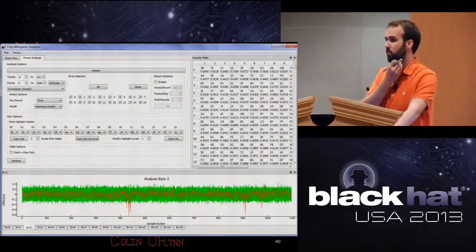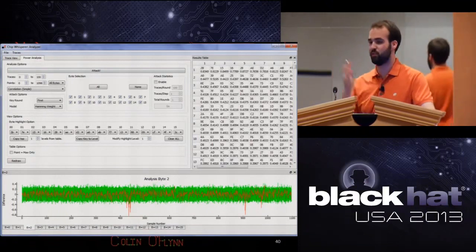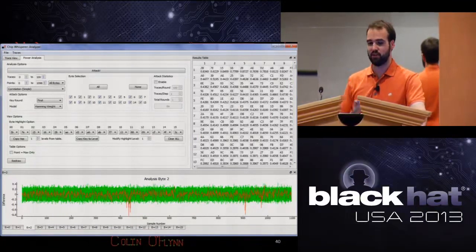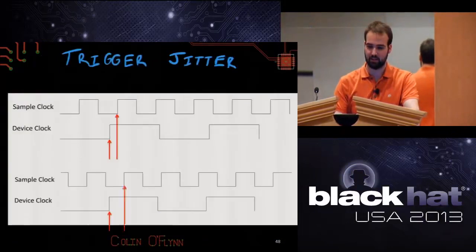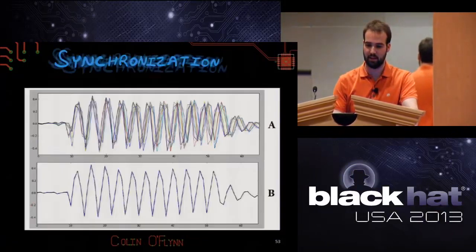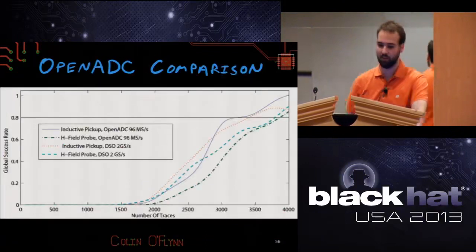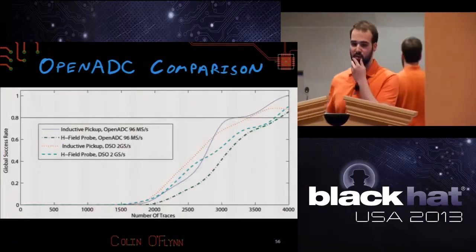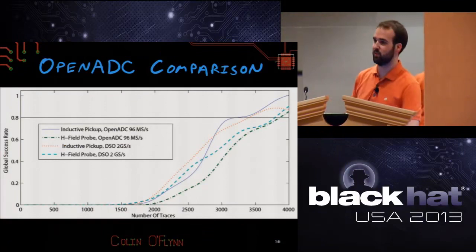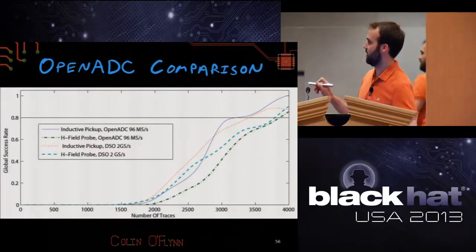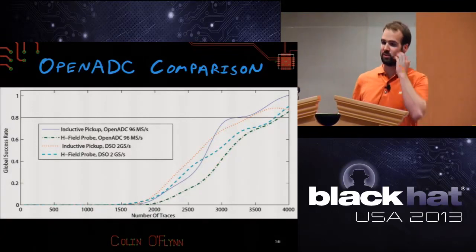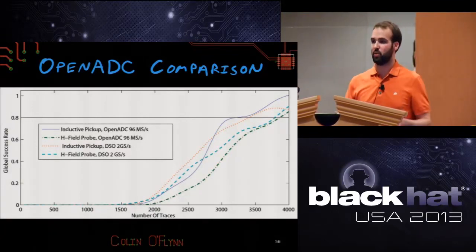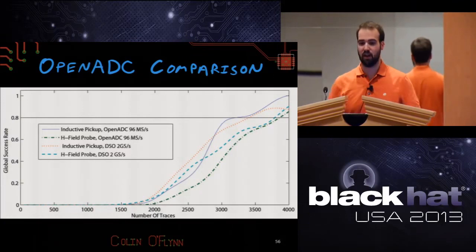Even if it's processing multiple bytes simultaneously? Yes, even if you do hardware AES and you do 128 bits at once, this works fine. In particular, where is it? This slide here, which I didn't actually talk about, is about an attack against a hardware AES implementation. The hardware AES is running at 24 megahertz, and it takes 10 clock cycles to do a full AES, which means it's doing all 128 bits at once on every clock cycle.